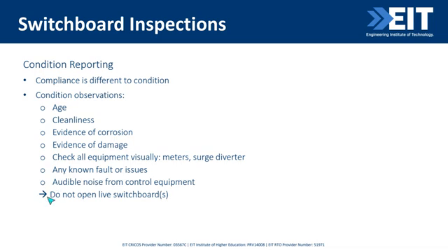But the key safety factor is you do not open a live switchboard, especially if internally it does not have segregation from you and things that are live.